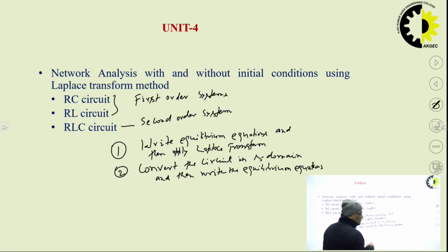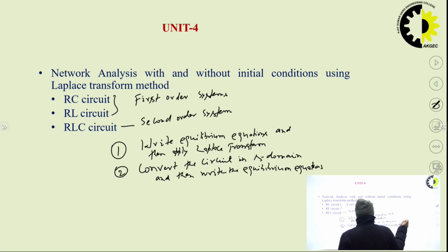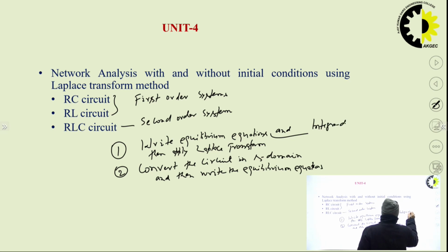So there are two methods to carry out the network analysis using the Laplace transform. Either we write the equilibrium equations, where, depending upon the type of circuit, we get an integro differential equation. To solve an integro differential equation, we apply the Laplace transform.